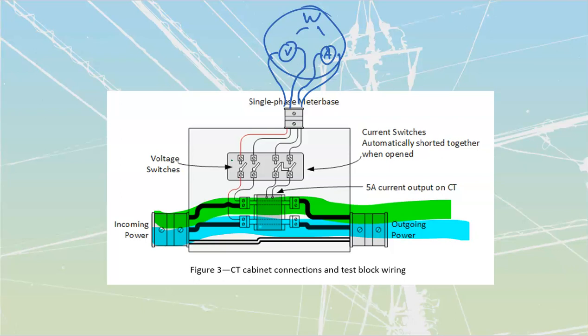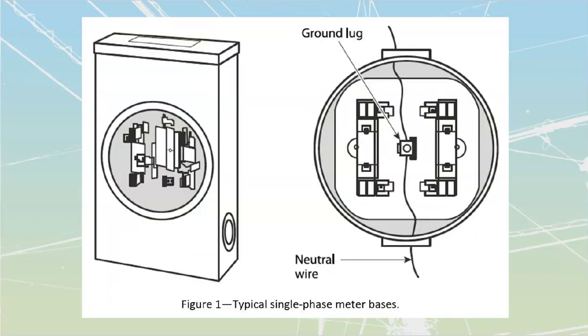Yeah, the CTs, we've talked about that. Don't ever pull them, and make sure that those terminals are shorted. It does not cause any issue. Let's just go back to the very beginning of this chapter over here, and there were just a couple of rules that we need to go over that deal with some commonly held misconceptions as well.